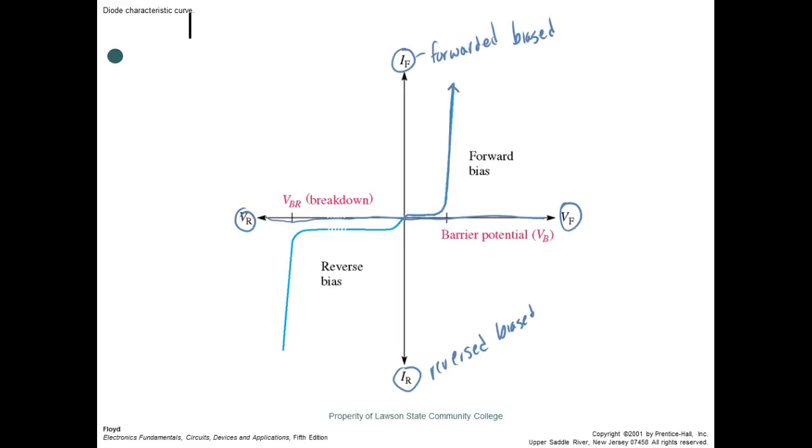But it's a semiconductor. It's got stuff in there. So that means the more current you put through it, it drops a little more voltage. The less current you put through it, it drops a little less voltage. So this slope right here is not straight up. Y'all understand that? So we never say it is a closed switch. We say it acts like a closed switch. But it does drop a voltage. Everybody okay?